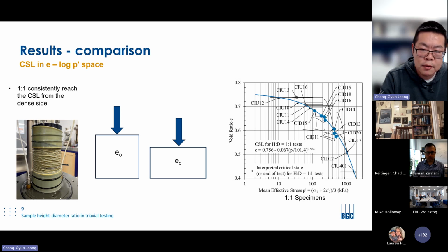Here's a similar schematic. It is similar to before, but those shear planes at 45 plus or minus phi/2 are not able to pass through and daylight on either side of the sample. So you end up with a much more uniform sample deformation where the entire sample is engaged and at the critical state void ratio, called e_c, at the end of the test.